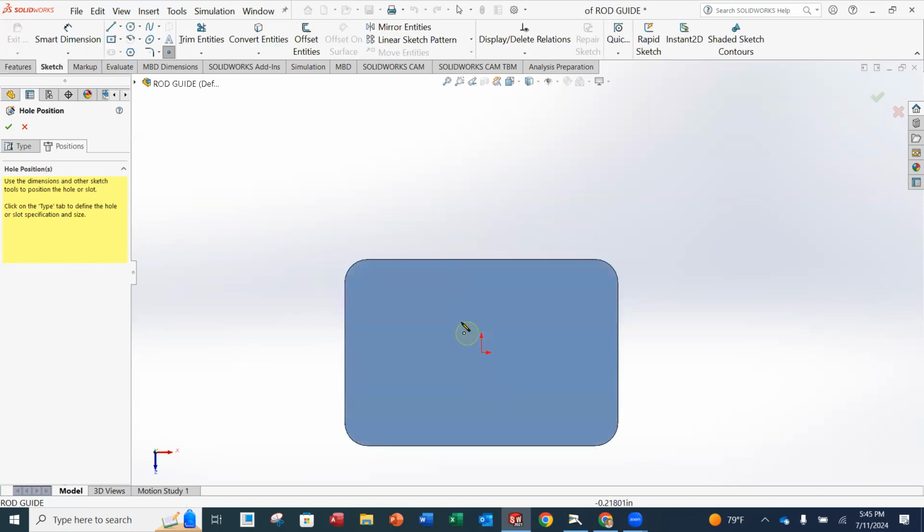Left click on that. And now you're going to notice that on the edge of your pencil, you have the opportunity to draw a hole. Now, what we're going to do is simply activate the radius. Don't click on it, just activate it by hovering over it. And you're going to notice that the center comes alive. So now when I go over the top of it, I'm going to put that first hole on that center. Now I can continue.